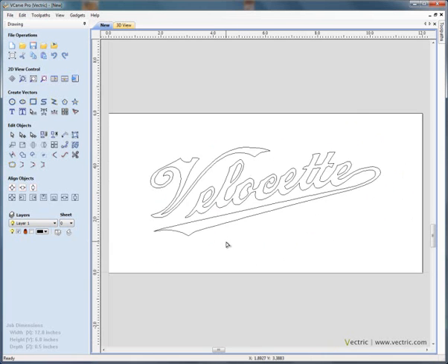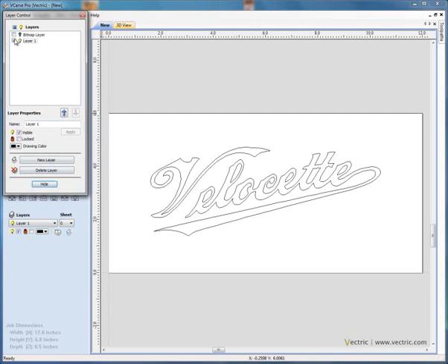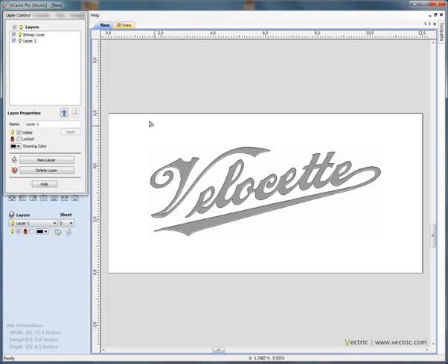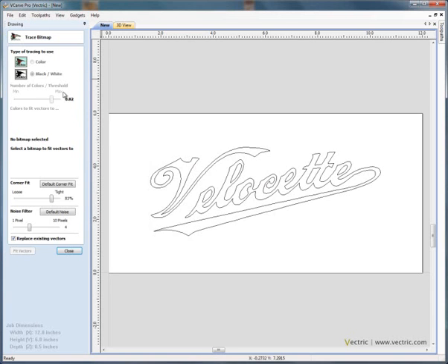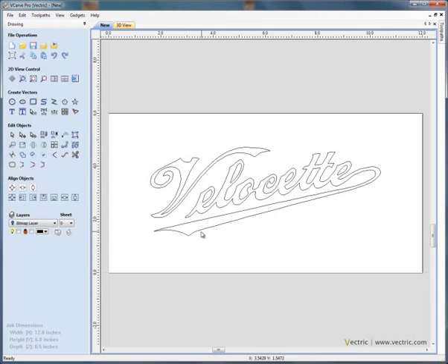So letter F to zoom to fit. So we've gone through importing a JPEG file. Using the import image file, this gave us the original JPEG or bitmap image in the two-dimensional view. With that selected, we then use the image tracing tool to fit the vector boundaries. Now that we've got vector boundaries, we can calculate toolpaths. Let's move on and look at another example.